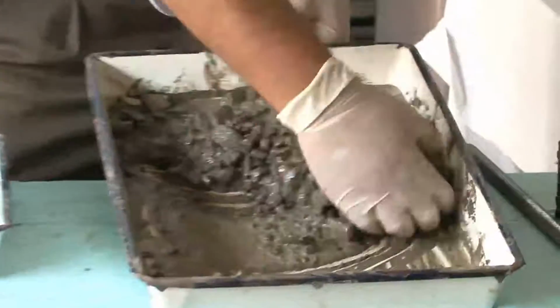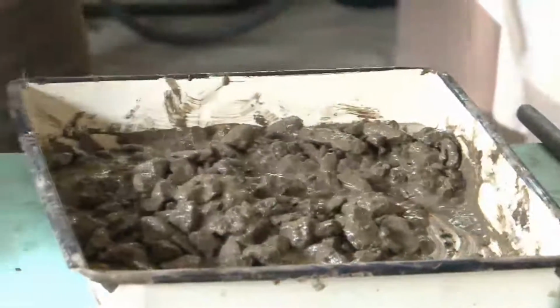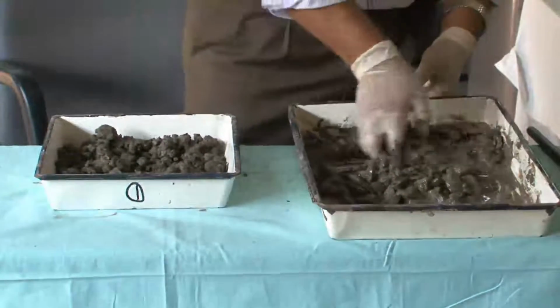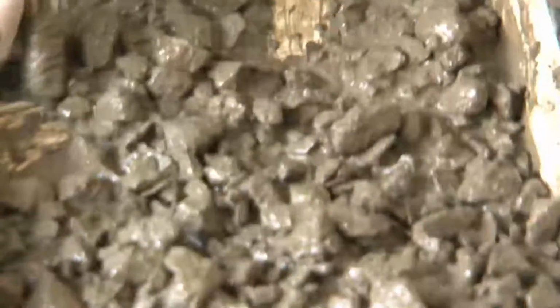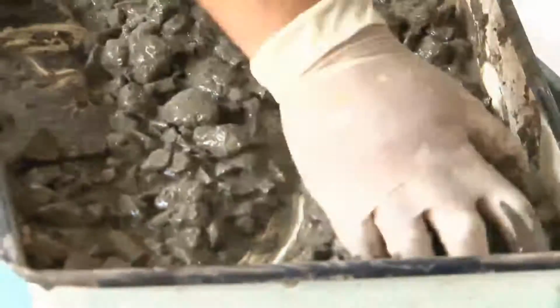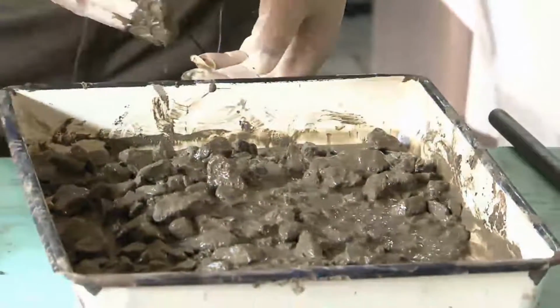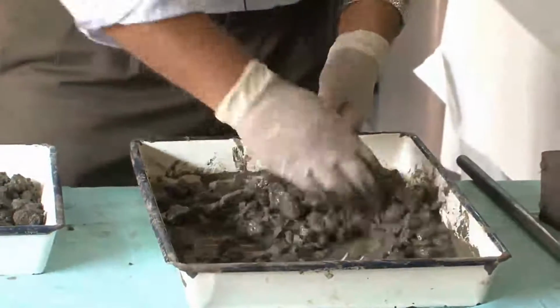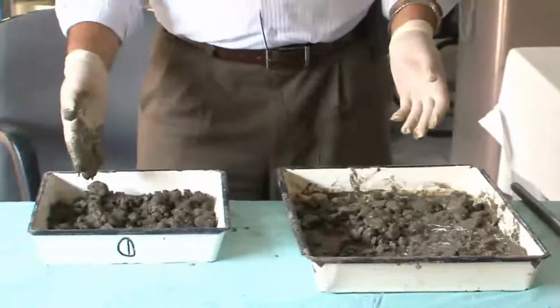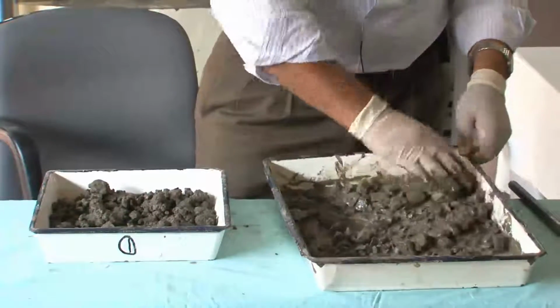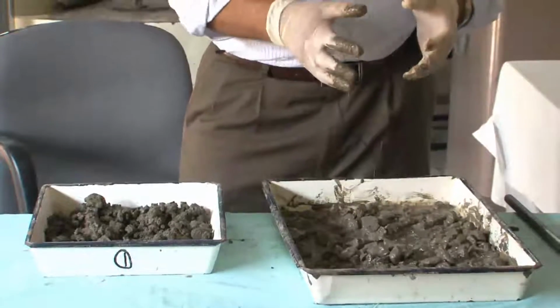Now, as I showed with the case of simply the paste, if we add a chemical admixture to the same concrete which is here, which is reasonably stiff, this concrete has been fluidized. It does not behave as a perfect fluid, but it is a higher slump concrete than this one. So, we are trying to show how chemical admixtures can be used to plasticize the concrete. Again, we can use the chemical admixtures to reduce the water demand, as we showed in the case of cement paste.